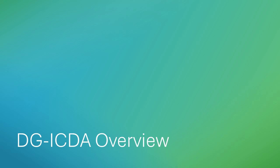Introduction to DG-ICDA, objective of the DG-ICDA methodology, scope and applicability, key concept. Water presence and accumulation, overview of the four-step DG-ICDA process. Step 1. Pre-assessment. Step 2. Indirect inspection. Step 3. Direct examination. Step 4. Post-assessment, advantages of DG-ICDA, limitations and key assumptions, conclusion and key takeaways.